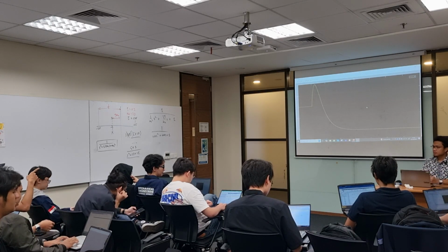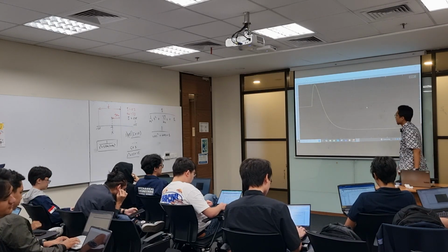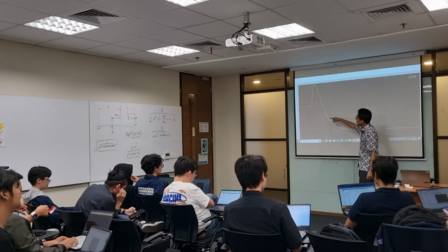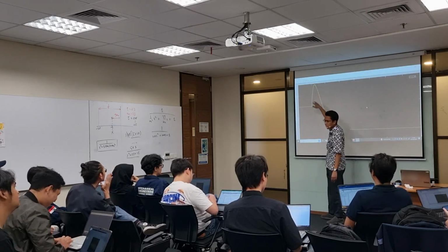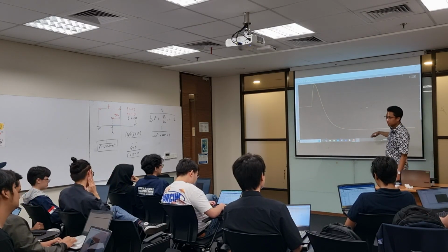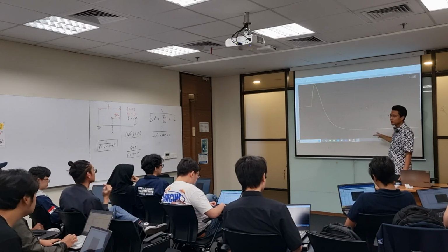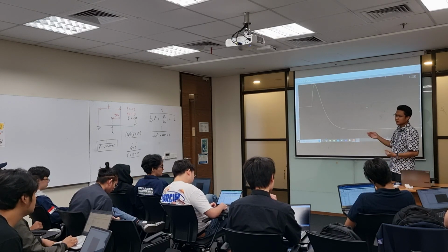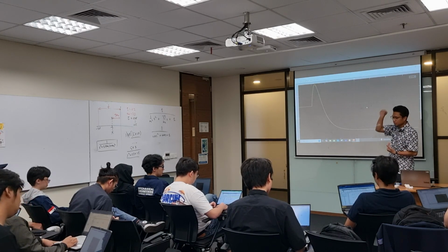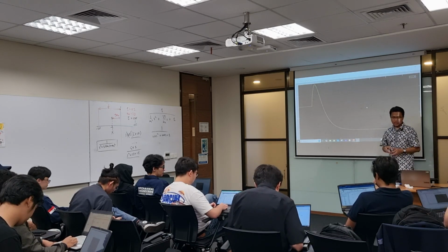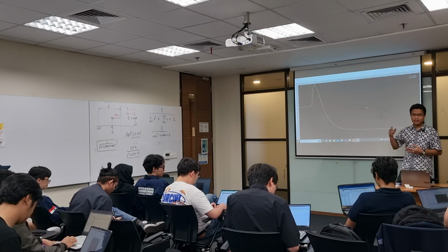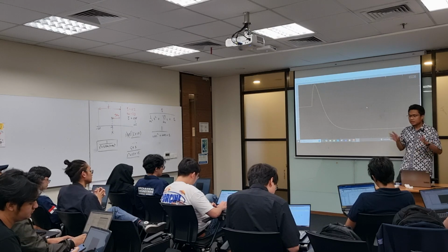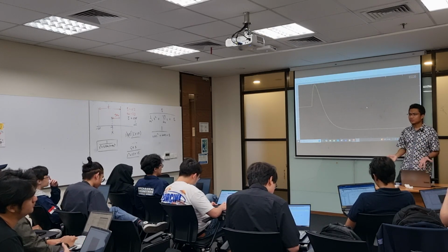Yeah, that means your final value is here. But then your system wants to go up in the beginning, but then finally your system has to go down. This is called the non-minimum phase system. Non-minimum phase system behavior is like this. At first, you go to the left, and then after that you go to the right side. So it happens when your zero is on the right half plane. It's not good, okay? It is stable, but not good.